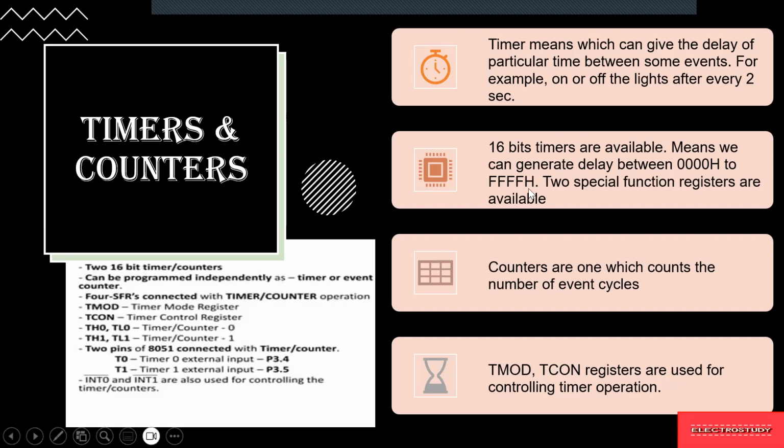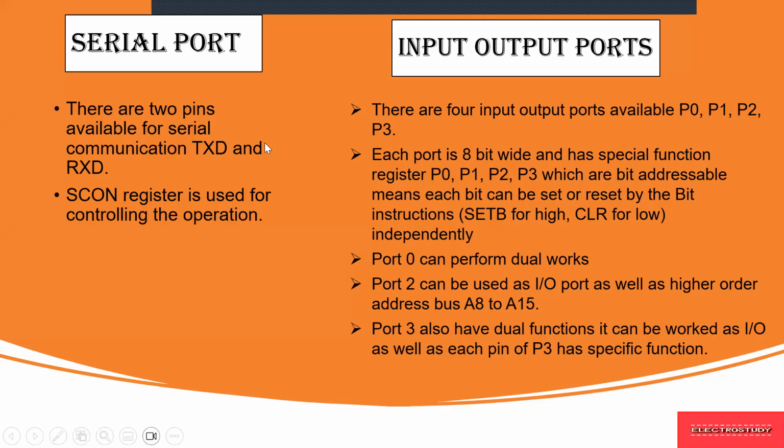And the timer has special 16-bit timers where the delay starts from 0000 to FFFF, that is lower bit to higher bit. And you obviously have two functional registers that we have already seen. Coming to the serial port and input output ports, the serial port is nothing but TXD and RXD, which I have explained, for transmitting and receiving of data. The special register allocated for the serial port is SCON. This is the one which will be controlling the operation.